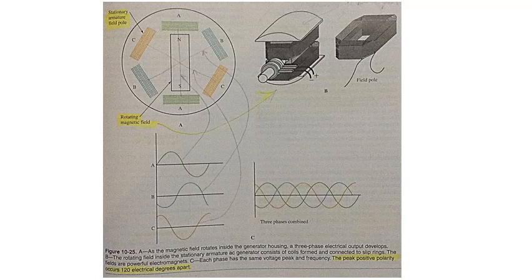The sine wave that develops from three-phase electrical systems is unique. The three-phase windings of the armature are connected as pairs. They are called phase A, phase B, and phase C. As the magnetic field rotates inside of the generator armature windings, 3 different sine waves develop. The 3 waves are 120 degrees, or electrical degrees, apart. See figure 10-25, part C.